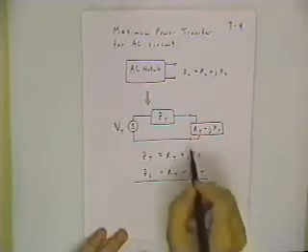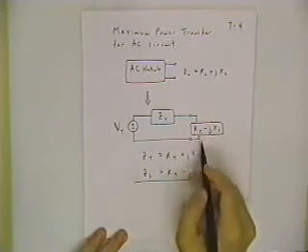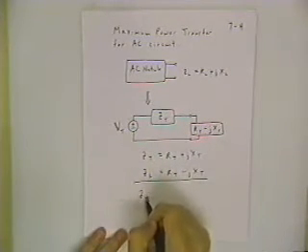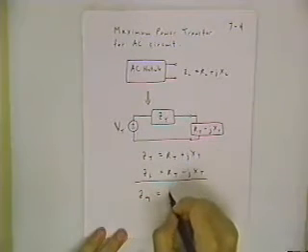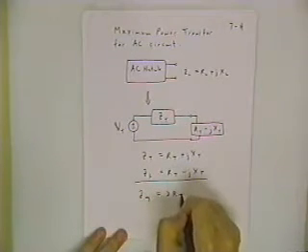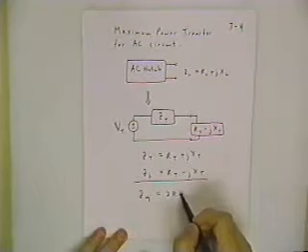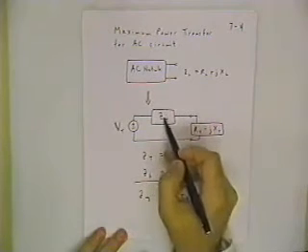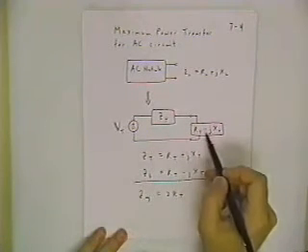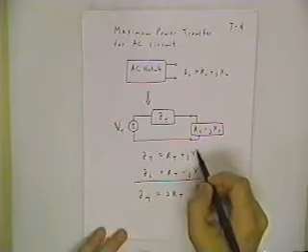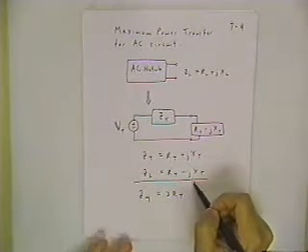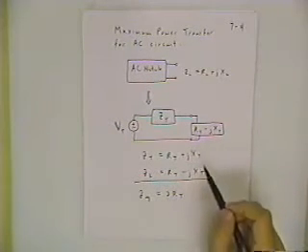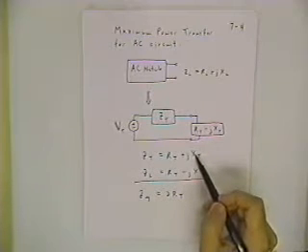And you notice what happens. These series connected impedances add together, Z equivalent gives you just a pure resistive load, if you include the Thevenin impedance and the load impedance together. The imaginary parts cancel out. And we're going to see in just a minute the imaginary parts represent power that's trapped within the components.